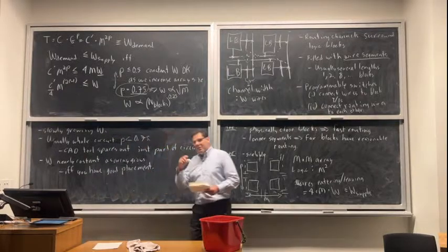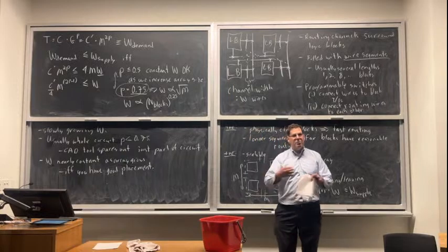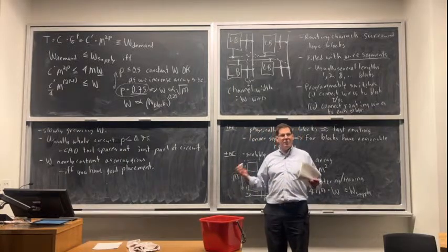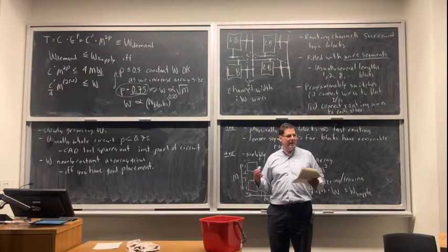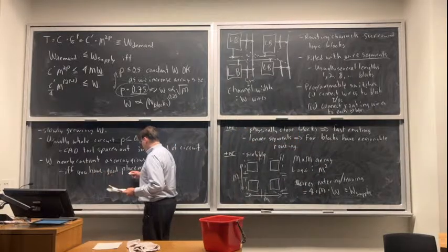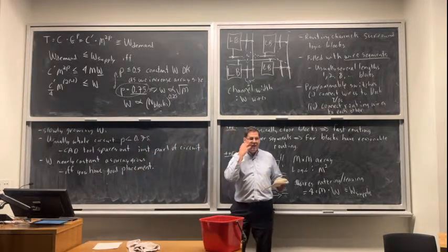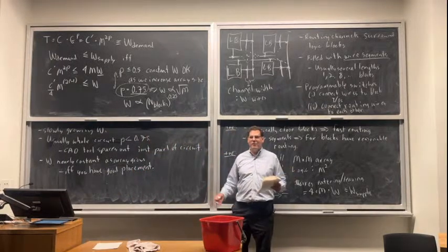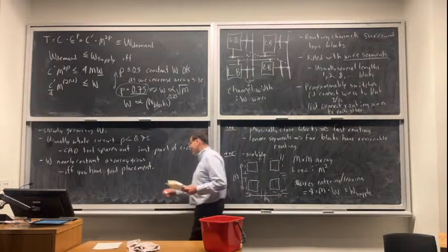So good placement means the CAD tool finds what's connected and puts them close to each other. And that's a computationally hard problem. It can't be solved perfectly in any reasonable runtime. So this is why FPGA companies spend a lot of money on CAD. They have big software divisions. Some of you may come from those software divisions because they need to have good placement.